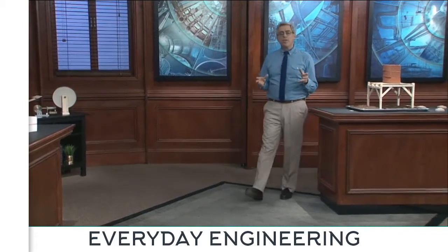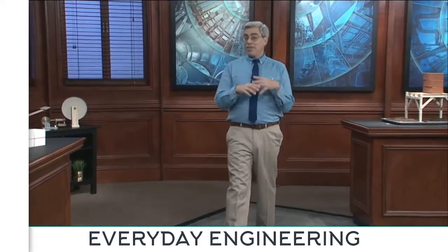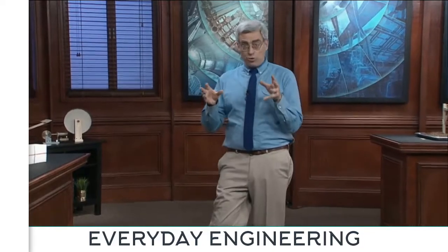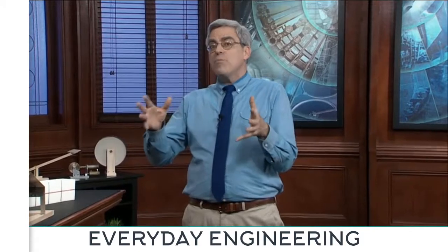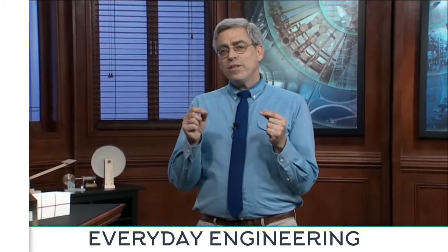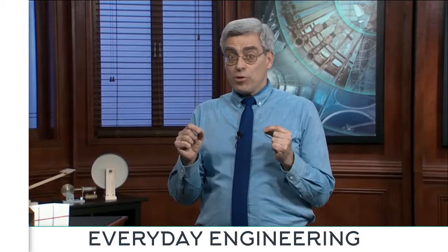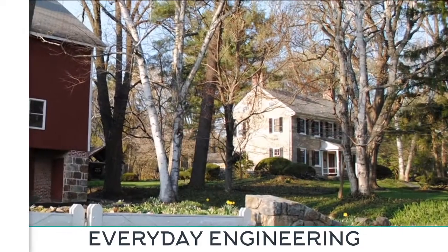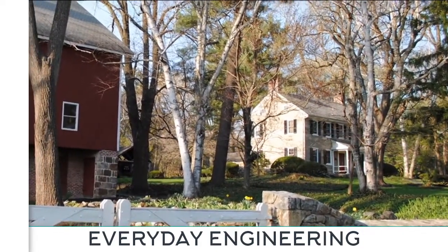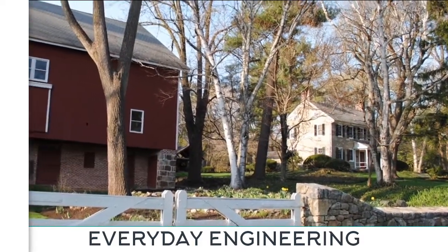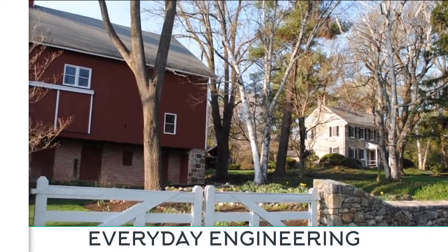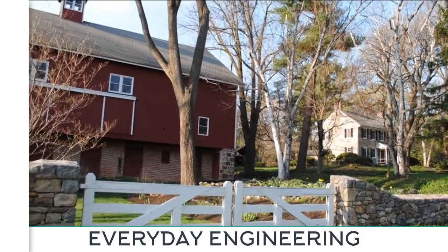Now, the heavy timber frame is a very versatile structural system, and it's generally less expensive to build than a traditional bearing wall building, particularly in regions where plentiful supplies of timber are available. But the all-wood construction of this timber frame is also less permanent, and those mortise and tenon joints require highly skilled craftsmen to fabricate. Like this stone farmhouse and its adjacent wooden barn, bearing wall and timber frame structural systems have coexisted side by side, each with its own advantages and disadvantages, for many centuries.